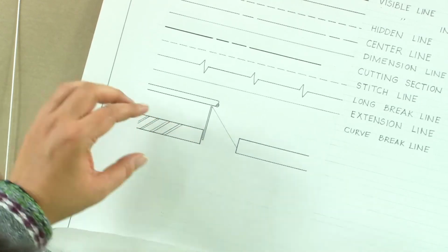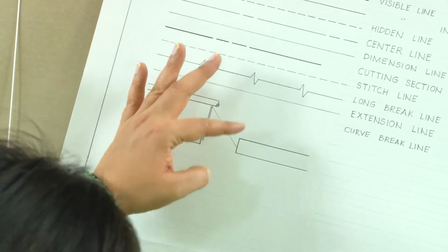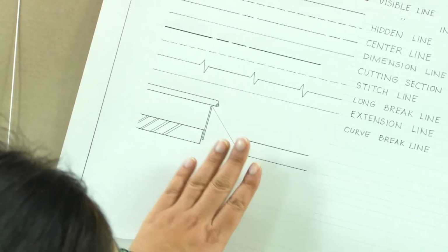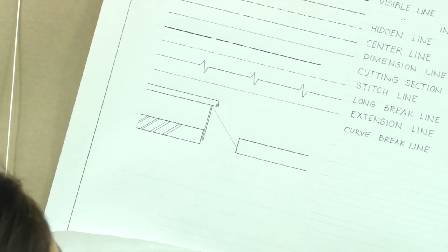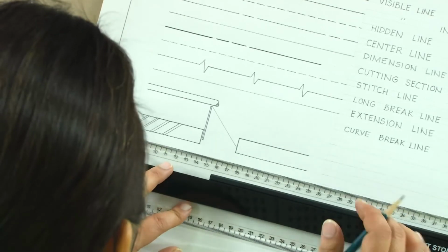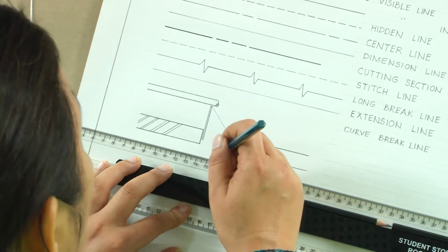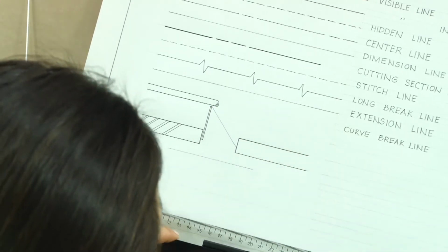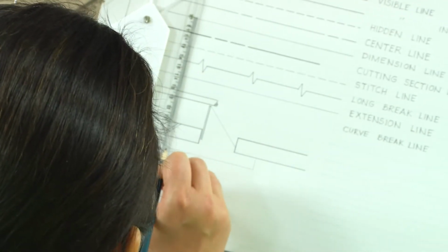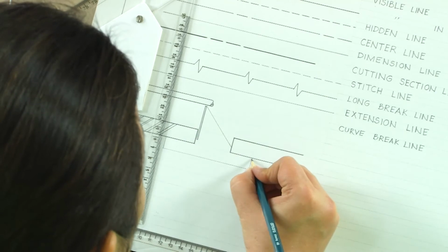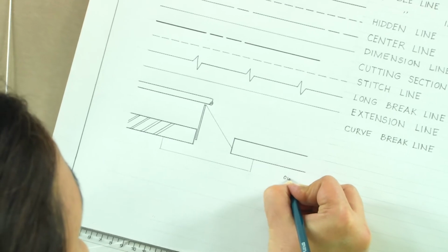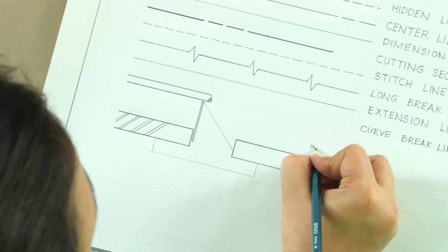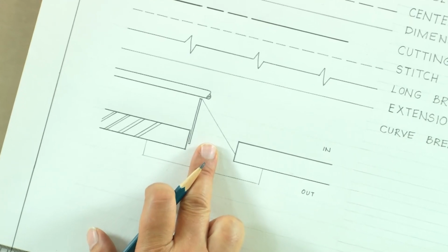Now this single door, if it does not have any step towards the inside or out, it implies that this is a door which is placed indoors inside the building. In case we want to mention that there is a step outside, we will make a line in the elevation which will be representing the step, not a staircase but just a single step. So this automatically represents that this is the outside and this is the inside. So this is the representation of a single door.